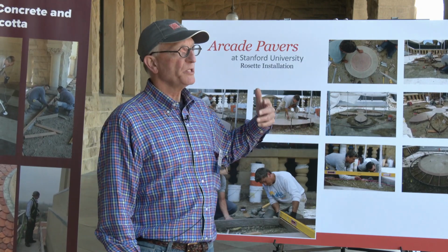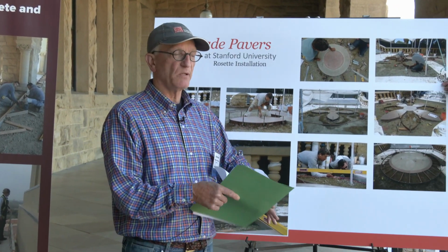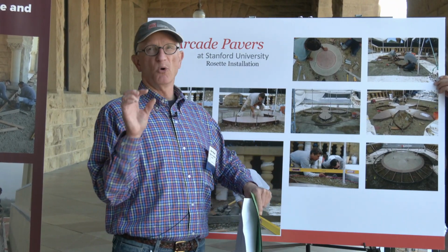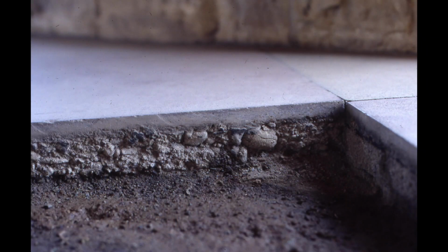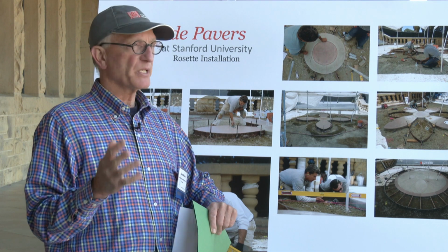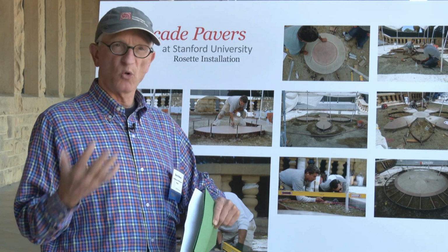We do the mixing essentially how it was done originally. So when we took up the pavements many years ago and examined them, we found that they were actually done in 2 pours. The first pour is about 3 or 4 inches thick. It's just a gray concrete. That is put down first. And then the color layer, which is about 1 inch thick, is put next. And the mixing and everything is the traditional way that it was always done.